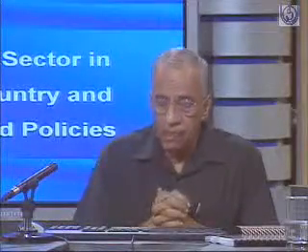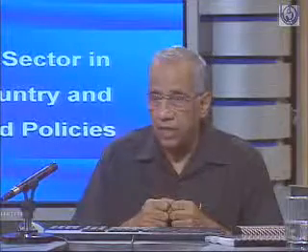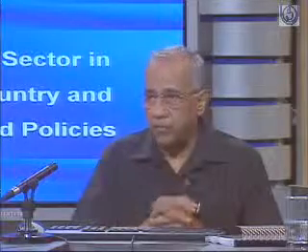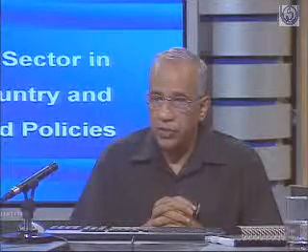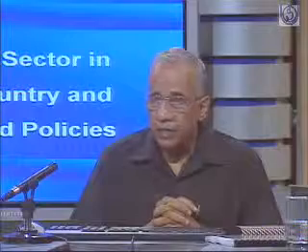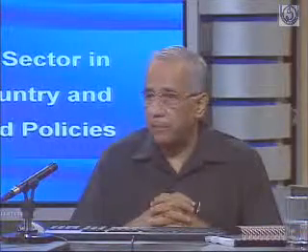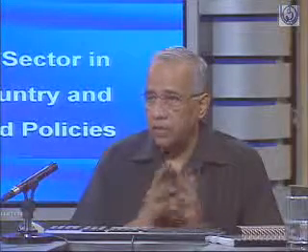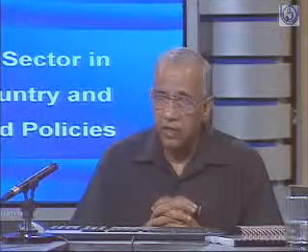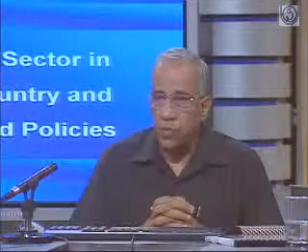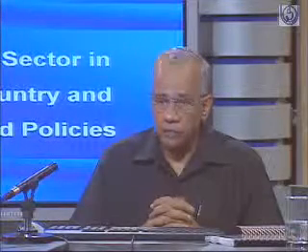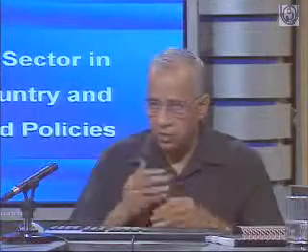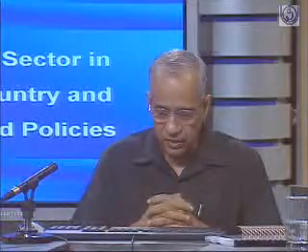Now this same machine, which if we just put in India will give you a number, say 30% efficiency, if it is taken to Germany, under the different boundary conditions, it appears to be slightly more efficient. Therefore, when you compare the numbers, they need to be converted into the proper boundary conditions of pressure, temperature, ambient conditions, the coal quality, and a whole lot of other things.